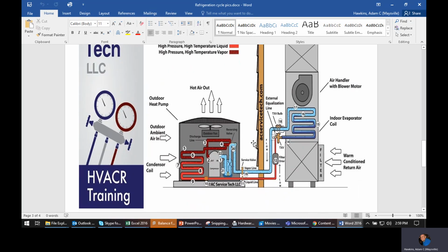We'll be doing these in lab. So your lab 6A covers the airflow side, and you'll be simulating those by putting things in to block the airflow or whatever. The other one simulates the charge side. So I'll actually have you put in a little extra refrigerant and then take out some of the refrigerant.